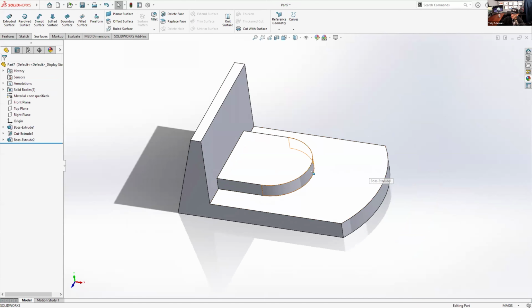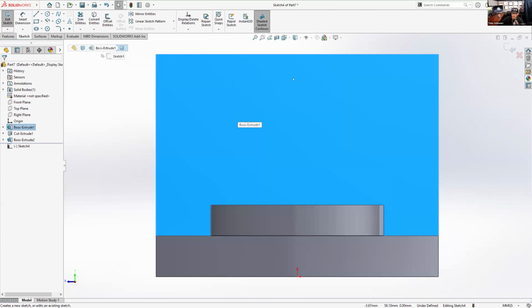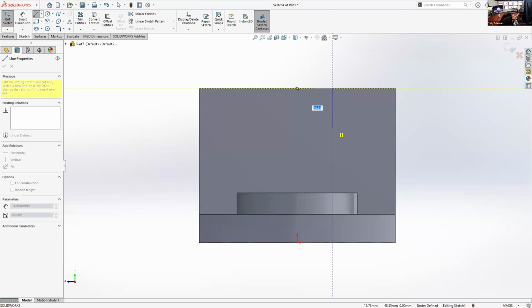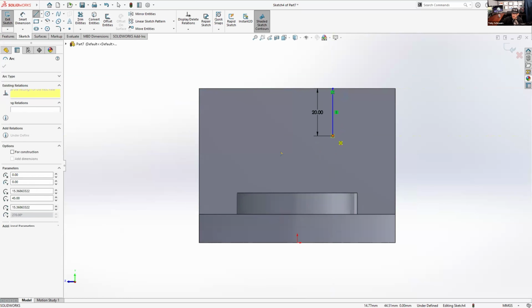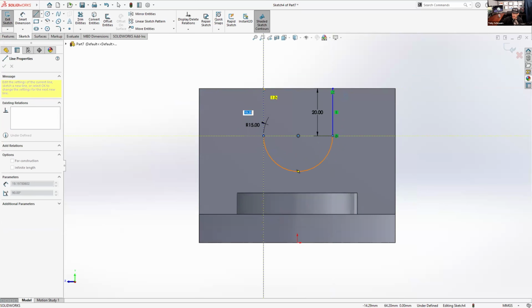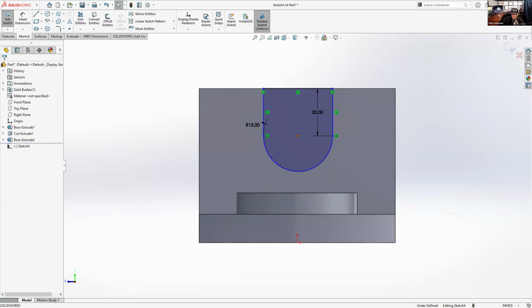Now, the other shortcut that's cool to know about in SolidWorks is when you create a cut extrude, the default cut extrude value is blind, but you can instantly change that by doing right click, which in the newer builds you kind of have to do a little bit more. But, well, let me just get this thing to be fully defined.